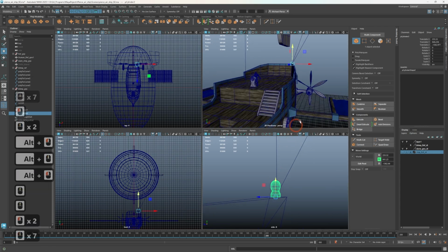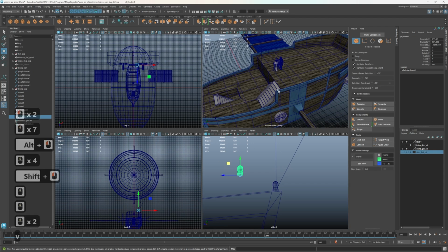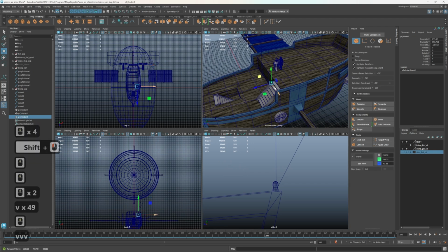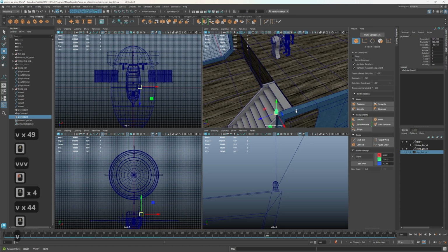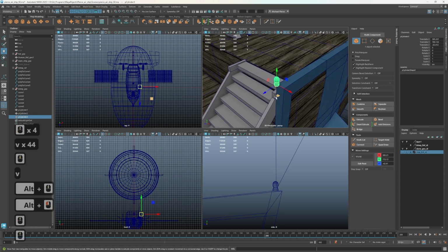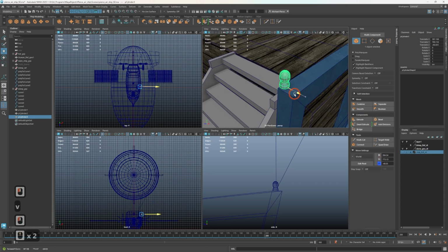And then I can now, apparently I didn't duplicate this. I'm going to snap it, holding the middle mouse, right? As long as you have the middle thing selected, you can snap it to any vertex you want, right? By using your middle mouse, the V key at the same time as the mouse wheel. And then I could just pull this over just like this.